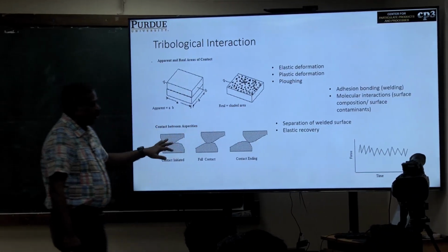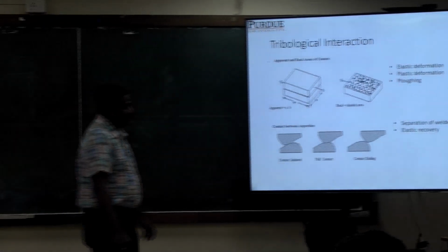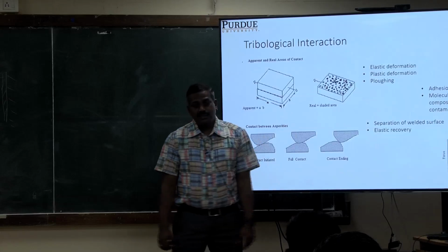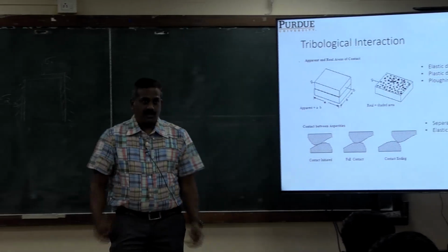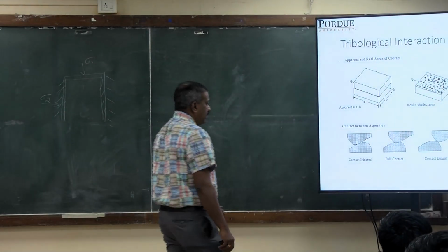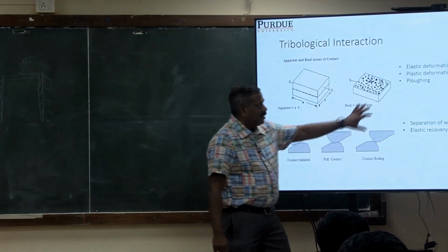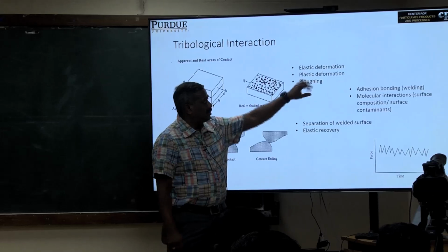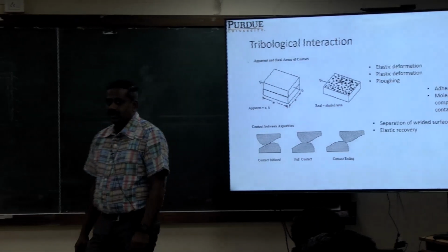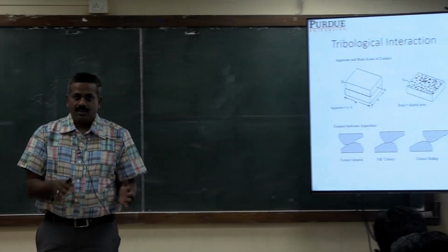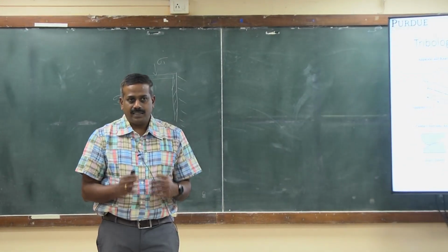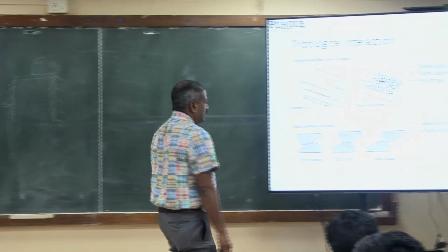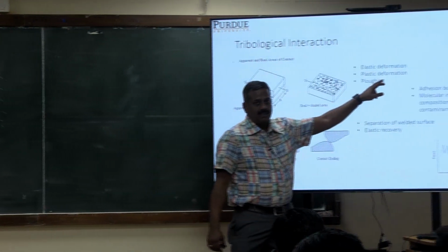What happens is, when one surface, for example one contact on this solid and one contact on this solid, comes in close contact during movement, it initiates a contact. There might be different phenomena occurring while it's moving. It starts from elastic deformation, right? If the normal force is not very high, it goes along with elastic deformation. If forces are high, then you might see plastic deformation, right?